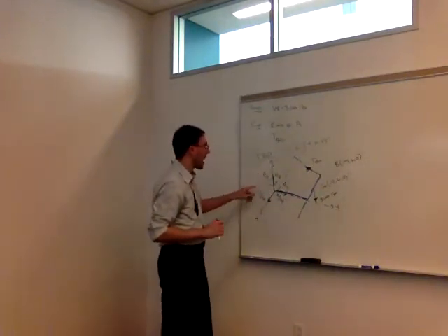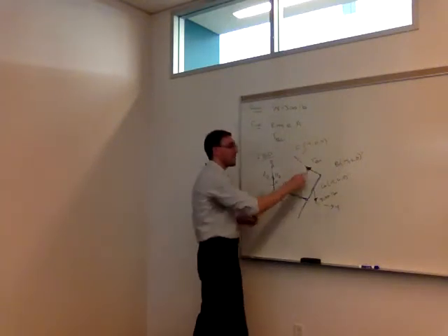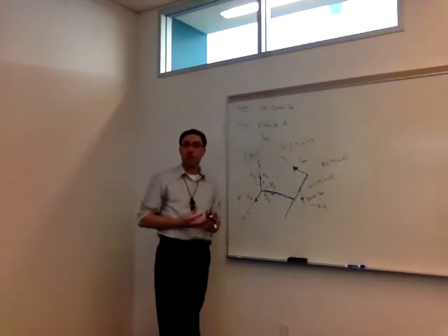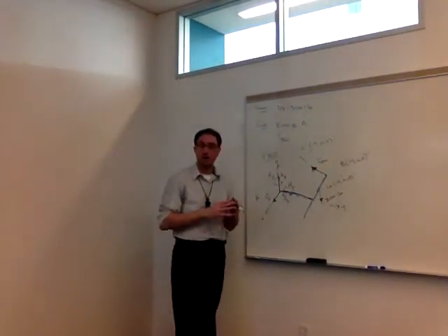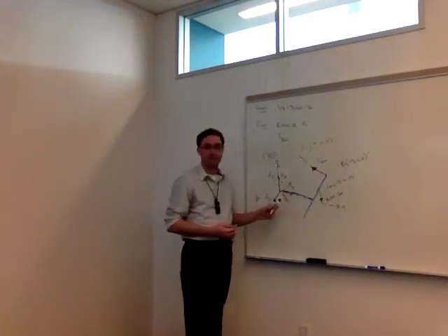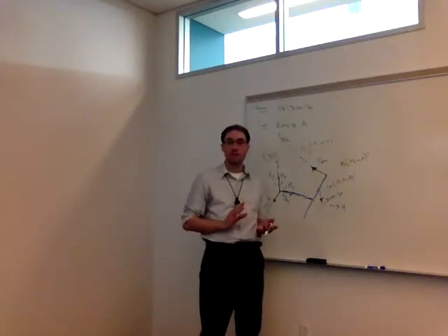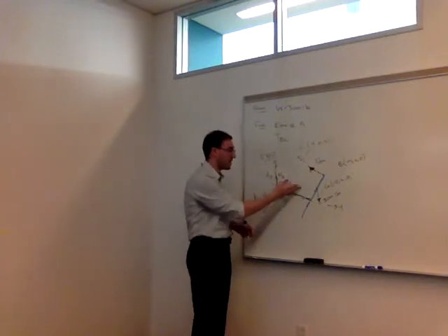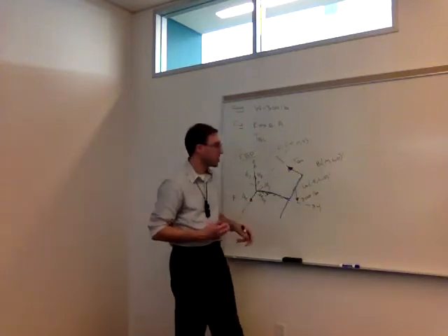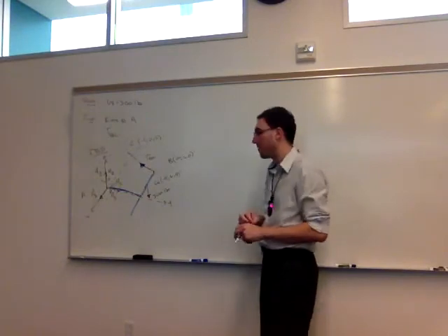So if we look at our free body diagram, we have 5 unknowns all at A, 3 forces and 2 moments. We have a 6th unknown, TBC, acting over here. So usually we'll have 6 unknowns in the problems. That's not always going to be true, but for 3D, that's usually the case. So if you count it up and you have 6, probably you're in good shape. If you have 5, that's not necessarily wrong, but you just want to double check. If you have 7, there better be like a spring in there or some other way of getting more equations, because in 3D rigid bodies, we can only get 6 equilibrium equations out of them.